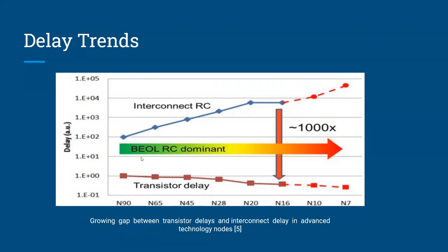However, the delay in the interconnect is increasing by a very large amount, because when we have a lot more devices, then a lot more interconnect has to be made, and then the network of interconnect becomes very complicated, and there are physical phenomena with the inductance and with the resistance happening inside the circuit that would further delay the switching speed in the interconnects.